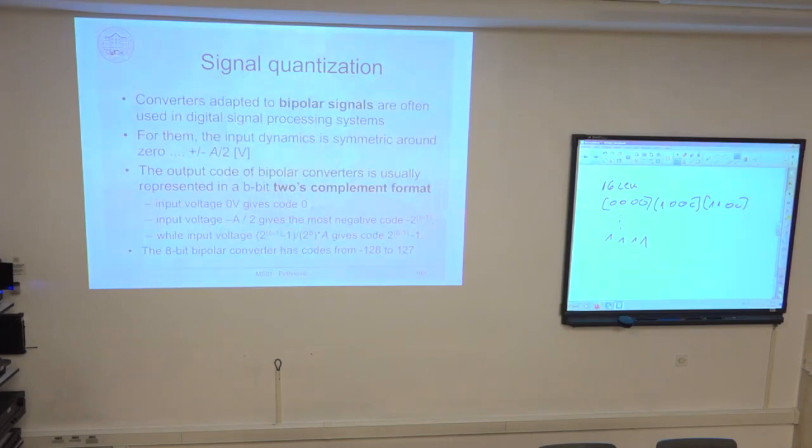Okay, and finally, usually AD converters are bipolar, and that means that this total range is divided into 2 equal halves, plus minus a half, to be able to represent positive and negative voltages. Typically, the input range is plus minus 1 volt for these converters. So I have to condition this input signal, whatever its value is, so that it is either amplified or attenuated, such that it is exactly around 0 plus minus 1 volt. And in this case, it is within the dynamic range of the AD converter.